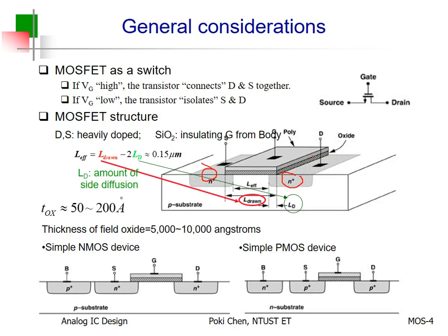But anyway, never mind, whether diffusion or implantation, all the ions or atoms don't go directly downward, perpendicular to your wafer surface, then penetrate into the surface. Forget about it. That is only in idea. In practice, the atoms and ions go not only down this way, but also that way, in many directions. And then you will get the so-called side diffusion here.